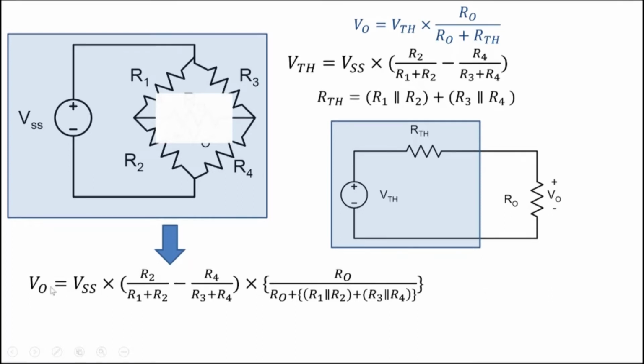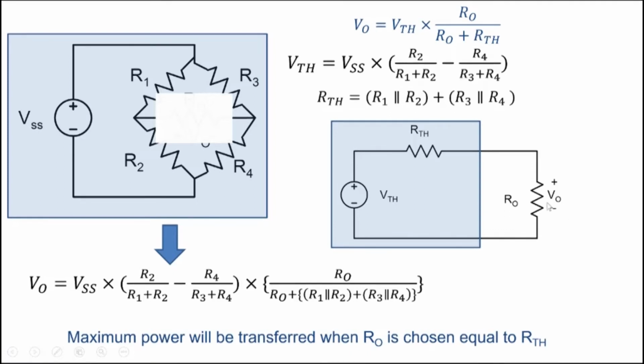If this expression is correct, then it says that this expression can be expressed in a circuit of this form, which implies that this entire circuit that you see here minus R0 can be represented as a voltage source and a resistor. And if you can do that, then our original problem of what R0 should I connect here in order to get maximum power dissipation, the answer is obvious. Choose R0 equal to RTH. So it becomes very simple. The result that we derived earlier can be applied to this particular circuit. R0 is RTH. And how were we able to apply?